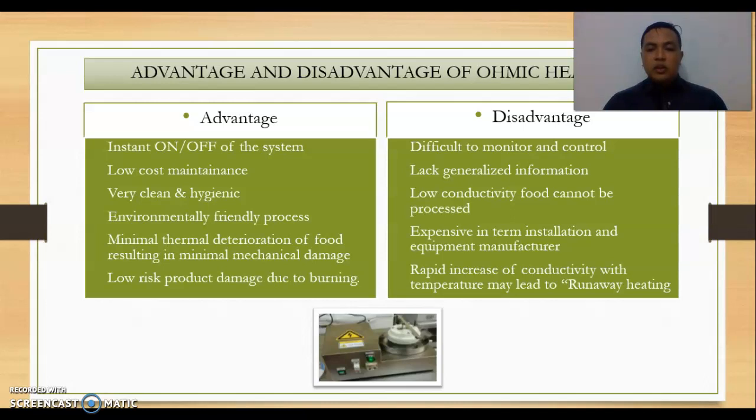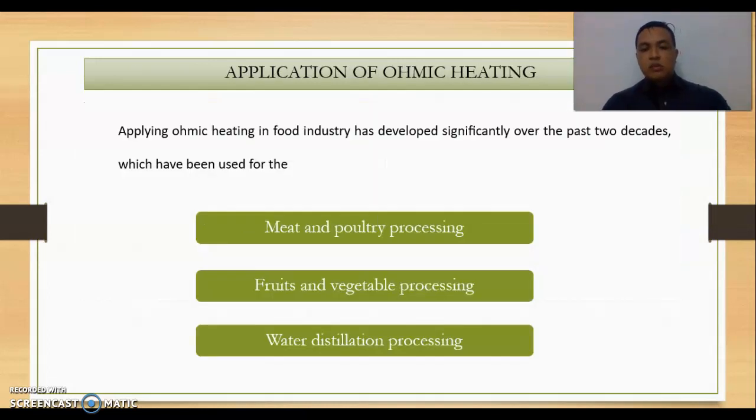The disadvantages of ohmic heating are that it is difficult to monitor and control, there is a lack of generalized information, low conductivity food cannot be processed, it is expensive in terms of installation and equipment manufacturing, and the rapid increase of conductivity with temperature may lead to runaway heating. So next, the application of ohmic heating, which is